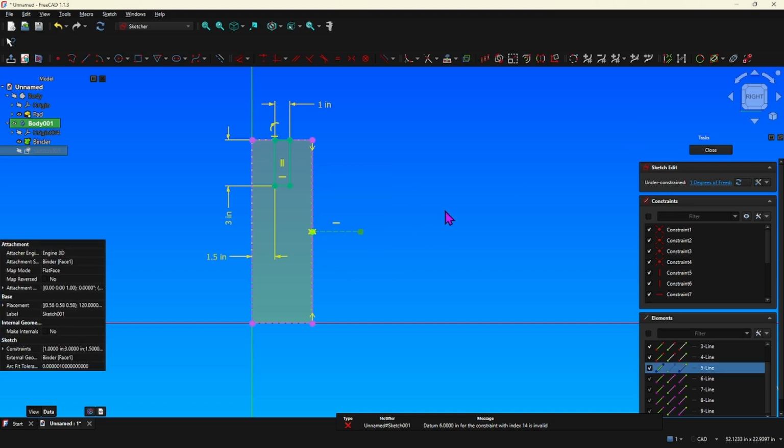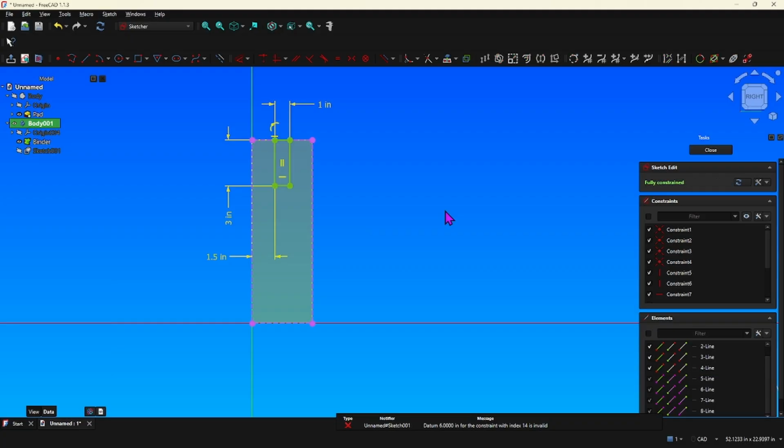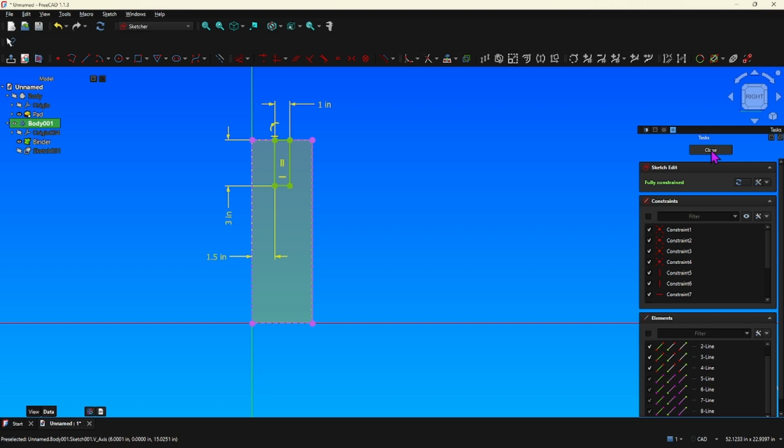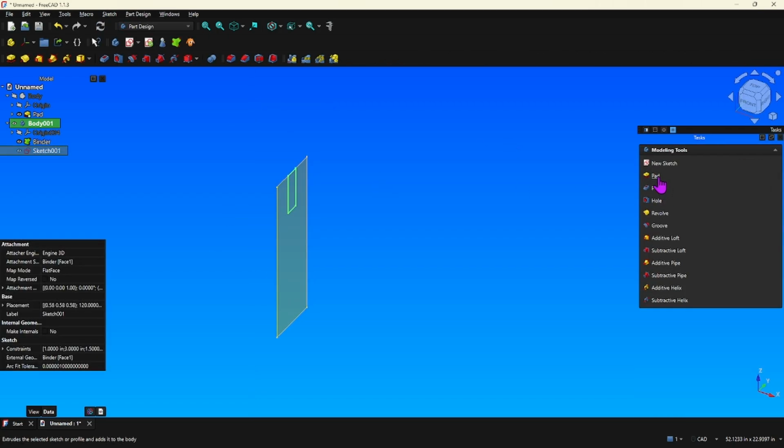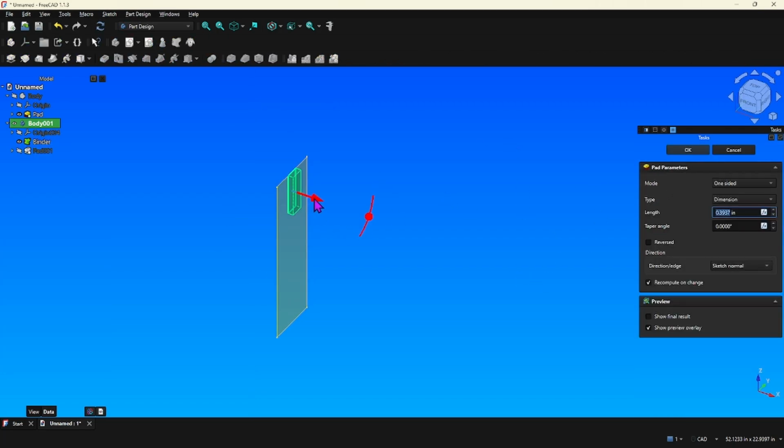All right, I'm going to go ahead and delete that. And who knows, maybe in the future FreeCAD will offer midpoint to midpoint selection to just kind of make it a little easier, like in SketchUp, in my opinion. So if anybody knows a better way, please fill me in. I'm open to learn. Okay, enough of that. I'm going to close that out, and now we can pad it. And over here, I'm just going to make it 12-inch length. Enter.